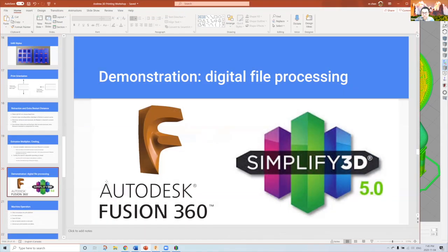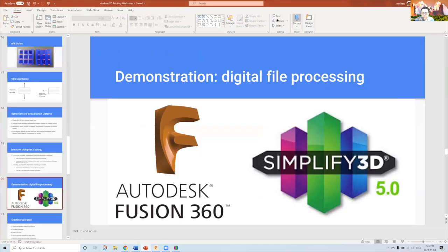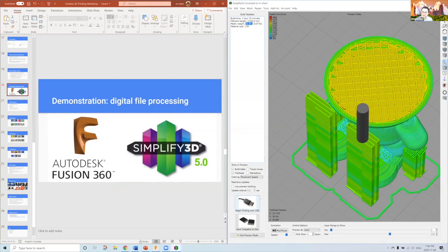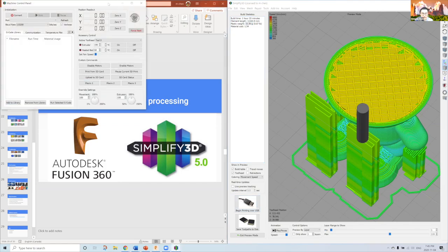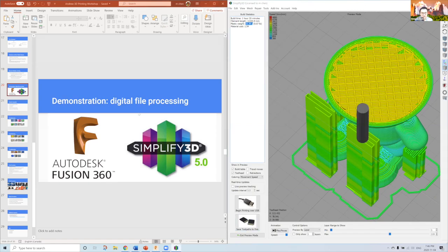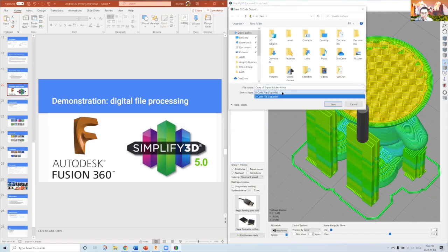Perfect. So now that we have our 3D print ready, right? Actually, before that, here's the last thing I want to talk about in this software. You can bring printing over USB, which is when you tether your 3D printer to your computer, so you can directly connect to the printer itself. It will have a control menu, right? When you press connect, it's going to let you configure some of the 3D printer functions, or you can save this to a USB drive. It's going to save as G code, right?